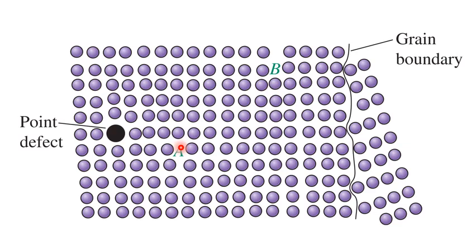We also can make the material softer by decreasing the number of dislocations. Decreasing the number of dislocations causes softening of the material. We can do that by raising the temperature of the metallic material to a relatively high temperature, but below the melting temperature, and holding it there for some time. This is called annealing.